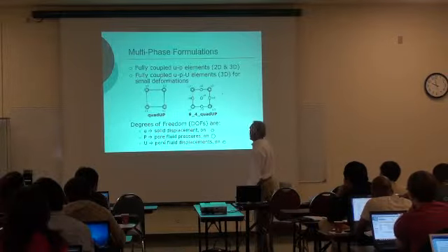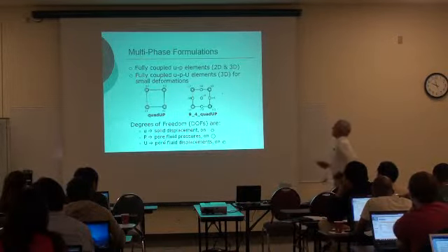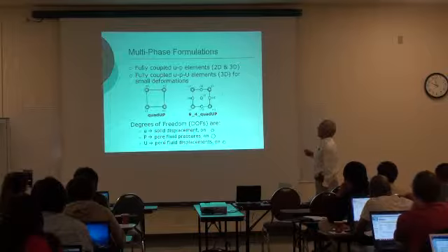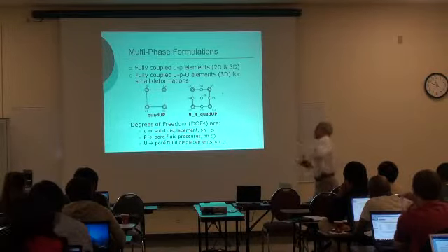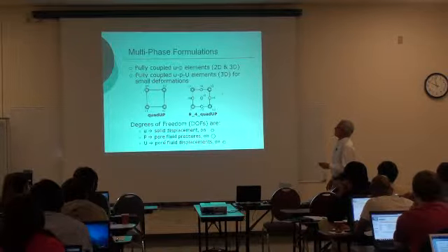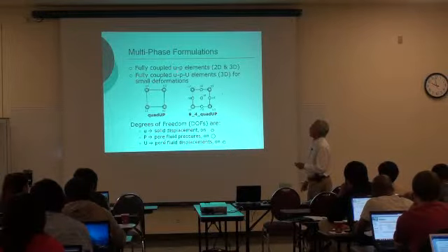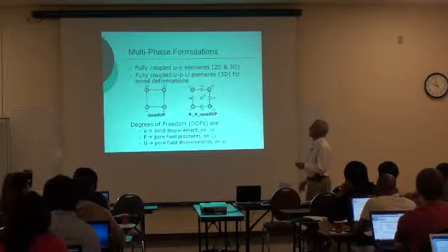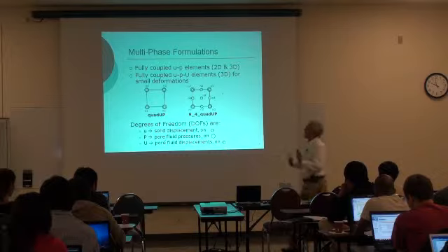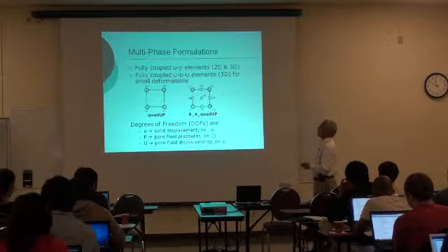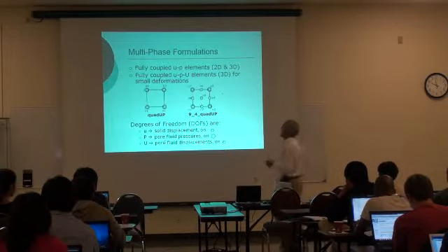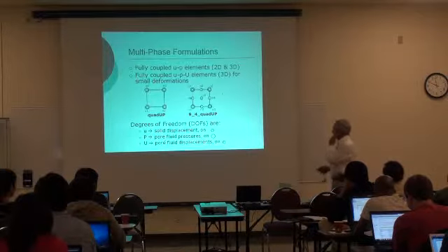Very simple. For multi-phase formulations, what we use is the fully coupled UP formulations. There has been some work done using what is called the UPU formulation in 3D and small deformations. Just to mention to you, UP means that we are going to track the displacement of the solid, and we are going to track the pore water pressure in the fluid. Now, more advanced formulations allow you to capture the displacement of the solid, the pressure in the fluid, and the displacement in the fluid relative to the solid too. So those are more advanced situations.